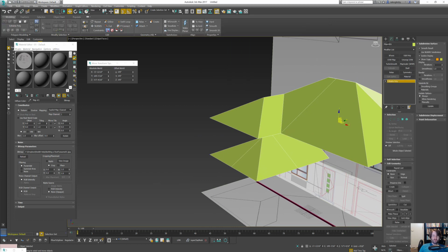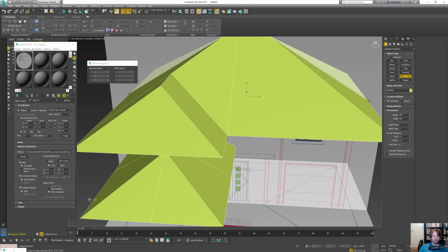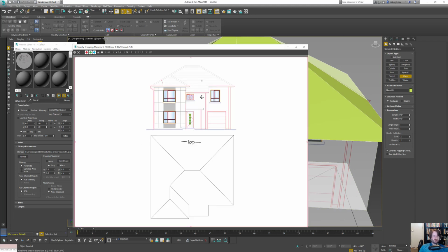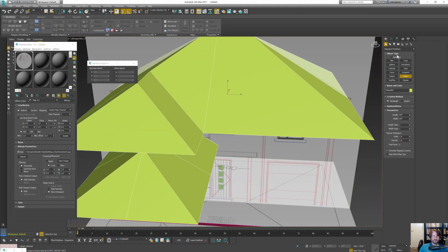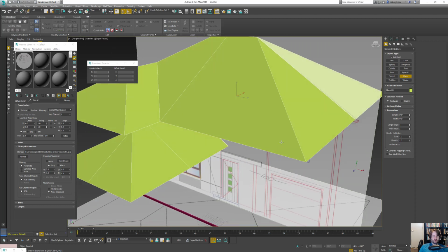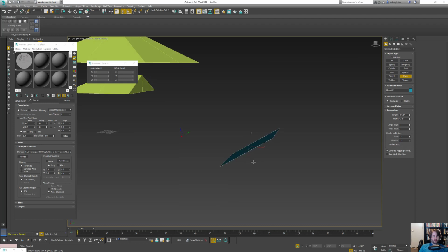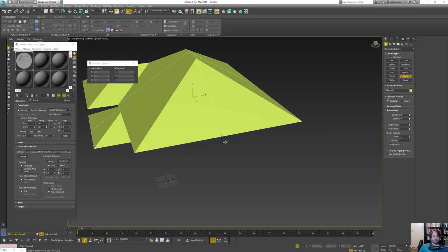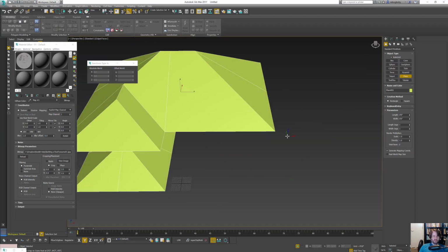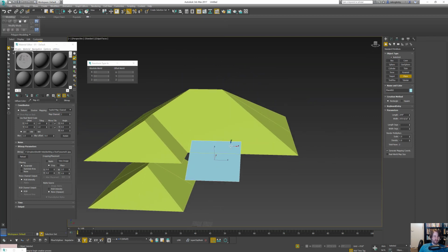Okay, this would be my workaround for this next problem that you are encountering, where you want the roof to slope down, and that is to do an auto grid and build a plane. Just build a plane right on. Oops. Okay, I'm going to isolate this and do auto grid. I don't know why it's going through. Let me turn off my snap and do it again. There we go. It was snapping to the ground plane is what the problem was.